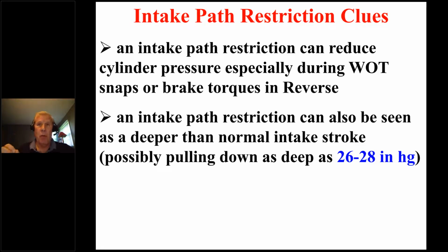There's another clue that you can see with an in-cylinder pressure transducer at idle, and that is how deep that intake stroke is. You've heard me say from the beginning of this session that probably the deepest vacuum that a gasoline engine is capable of is maybe 26 to 28 inches. More commonly 20, 21, 22. There are some that bump into 23, 24. That's not typical.